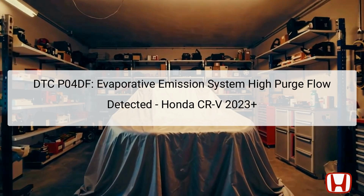DTC P04DF indicates a malfunction in the evaporative emission (EVAP) system, specifically noting a high purge flow. This is typically detected when the engine control module (PCM) perceives a discrepancy between the pressure from the evaporative leak check module (ELCM) sensor versus the barometric pressure (baro) sensor. Both sensors play a crucial role in monitoring the emissions from the fuel system.